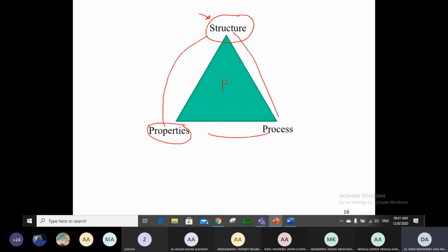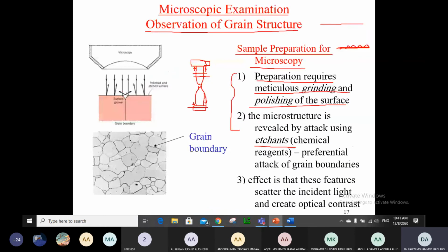So what does that do? That creates actually a groove at the grain boundary. The atoms get eaten there at the grain boundary faster than within the grain. So what does that do? It makes what we refer to as channels there. This channel, which you can see there, is made by the agent which we are adding.